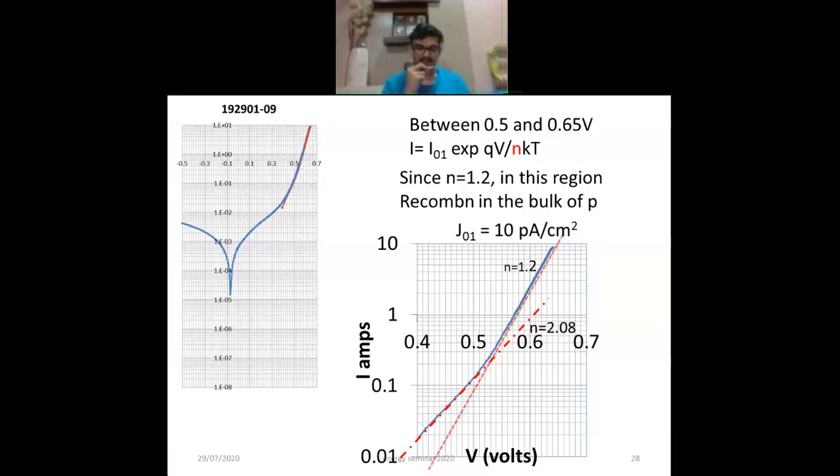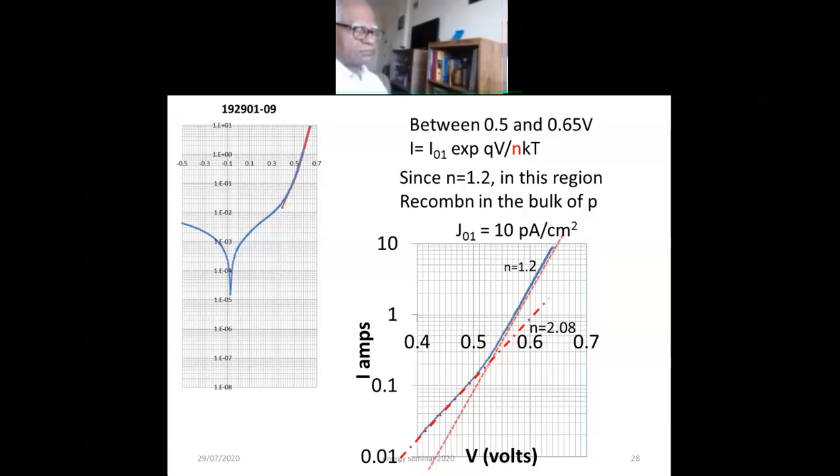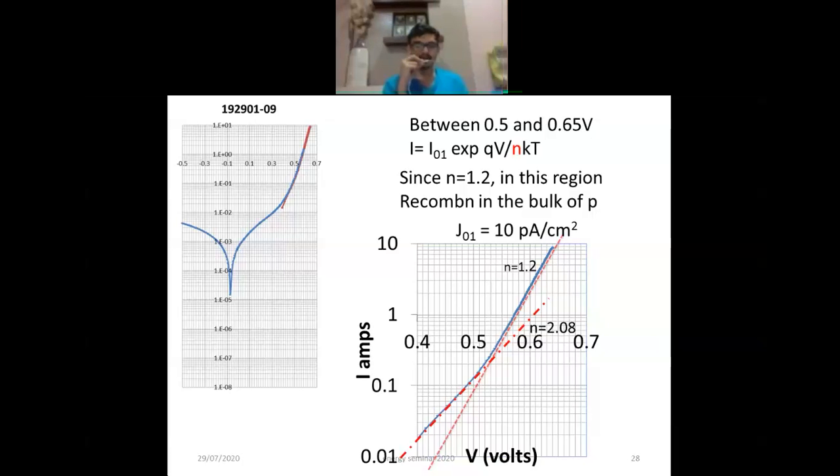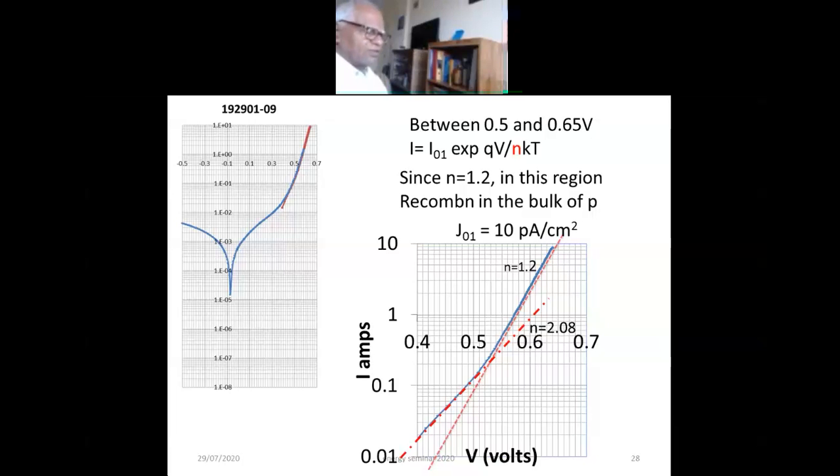So there's another question. This comes from Vandana. She says, is it possible to convert the other frequencies of the electromagnetic spectrum to the band gap frequency of a solar cell? Like this could boost its efficiency. Okay, so obviously you want to convert the part that is not absorbed. So I don't know how you will actually do that except by 2-photon absorption, but for that you require very high intensities.